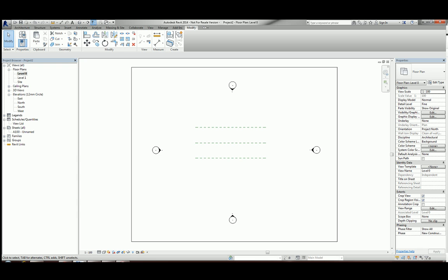And today I'm going to talk to you about walls and the location line that you specify when you're actually drawing a wall in. It can lead to some confusion between designers and Revit users as to the best location line to use. If you don't use the correct location line, it can cause headaches moving further on in the project. So hopefully what I'm about to show you is going to clear up a few things. Just bear with me on some of it because it's going to be a little bit talky.